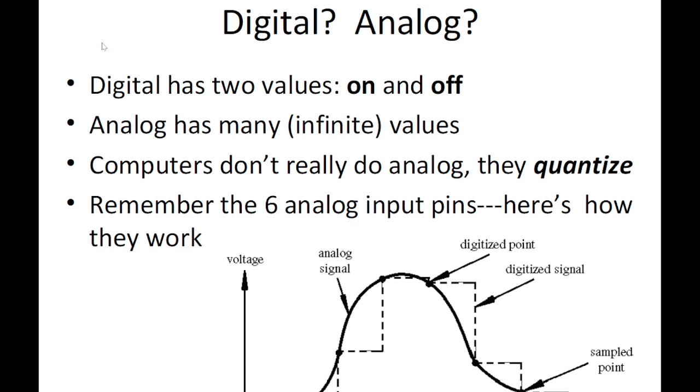When I'm saying voltage level 1, it means that the voltage level can be 5 volts, 3.3 volts, 1.8 volts, 2.7 volts, with respect to the zero voltage, which very commonly is close to ground, but not always necessarily. That zero voltage can be a negative voltage. For example, my zero voltage is negative 5 and my plus voltage is plus 5.